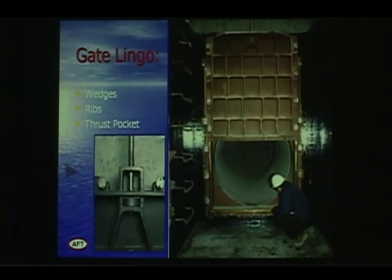A cast iron gate is cast. That means that there is a pattern, typically a wood pattern, that is used in the casting process. A couple things that you'll note is, in order to get some strength, you have a number of ribs. The more ribs, the deeper they are, the stronger the gate is. We've got a couple pictures of some pretty high head applications with a lot of big, deep ribs.